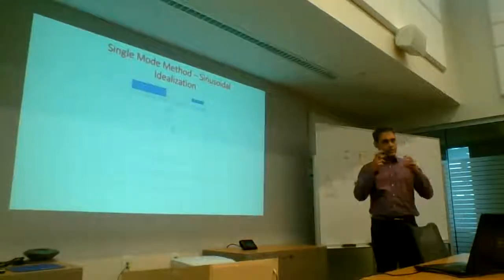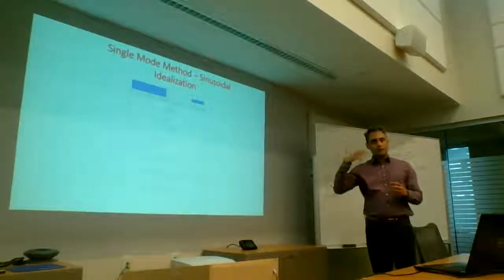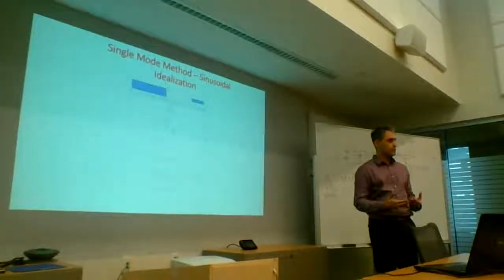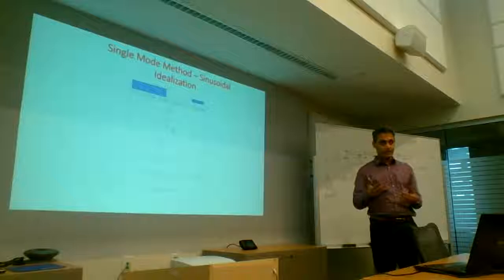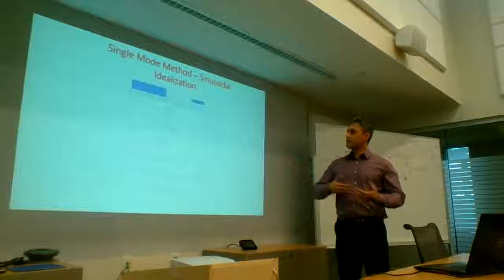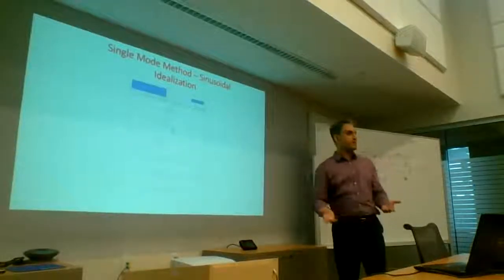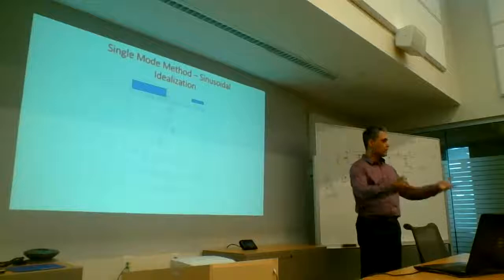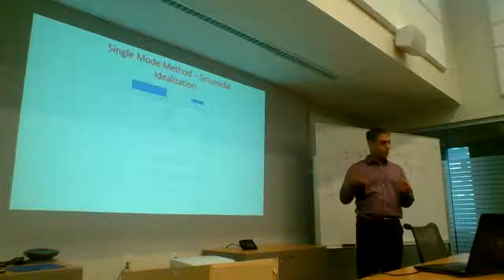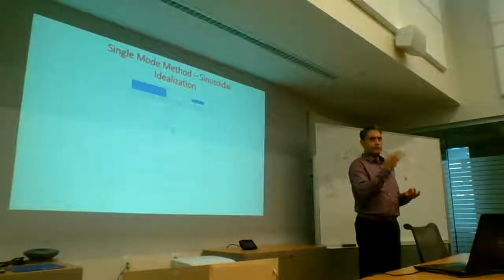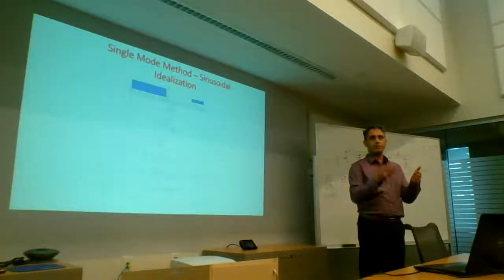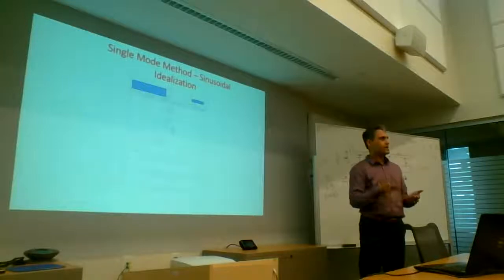So do those little checks, and then once you've satisfied yourself that your numbers are making sense, then you can rely on the software. Just don't rely on it blindly. But I also don't want to say these are useless methods. I also don't want to overemphasize their importance, because you have to do the work to set up that model, unless it's so simple, like the uniform load method, which I think is probably better, where if you can just come up with a 3EI over L cubed type formulation, you get the stiffness right away, you get the period, carry on.